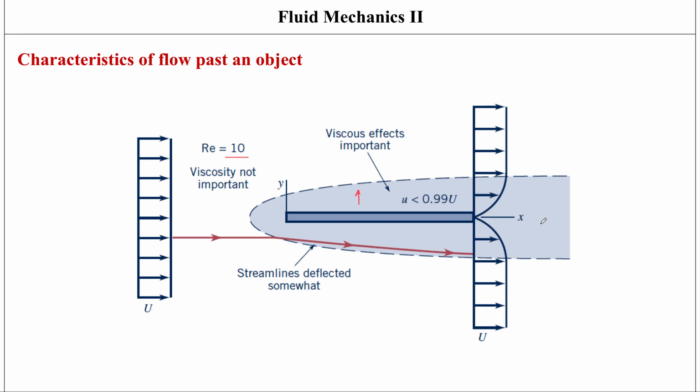Okay, so you don't need to travel very far away from the flow now to find a point where the velocity is going to become higher at a much faster rate than in the previous case, and that means, just to put it in simple words, that the boundary layer is going to be smaller as well. Okay.